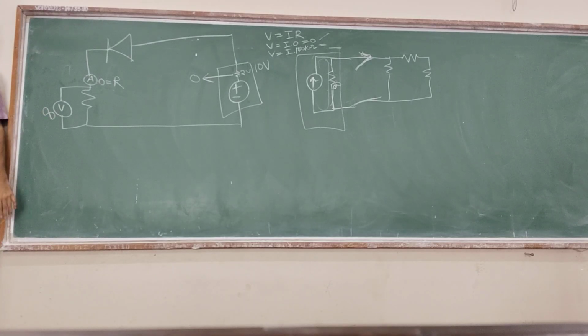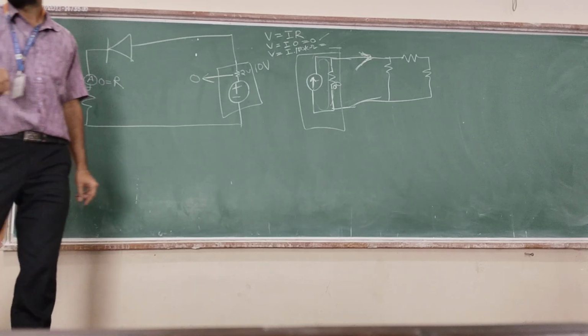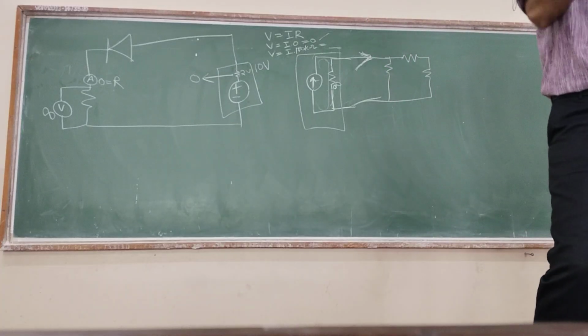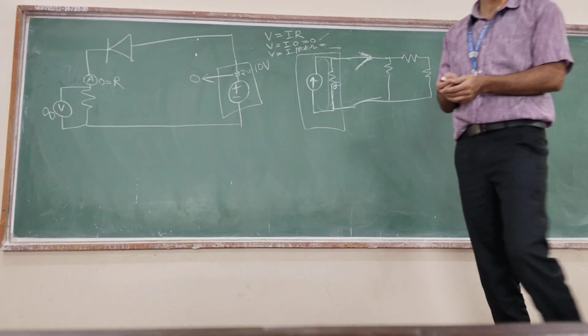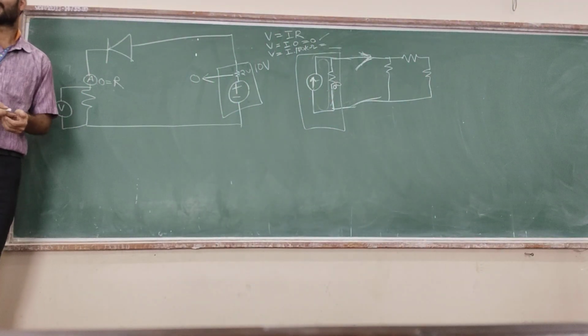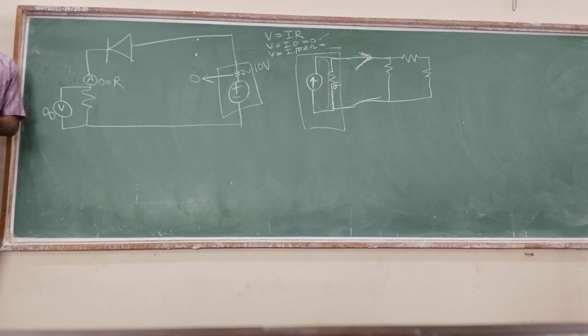Now this one. Resistance of voltmeter. What is the resistance of CRO? What is the resistance of CRO? You have used it. You haven't used it? Use the CRO, how much is it? It is written there, where you connect the probe, it is written there, you haven't seen. Who observed? It is very high. Mega ohms, 20 mega ohms. Go check in the lab. Okay. So voltmeter resistance should be ideally infinite, or practically too high, very large.